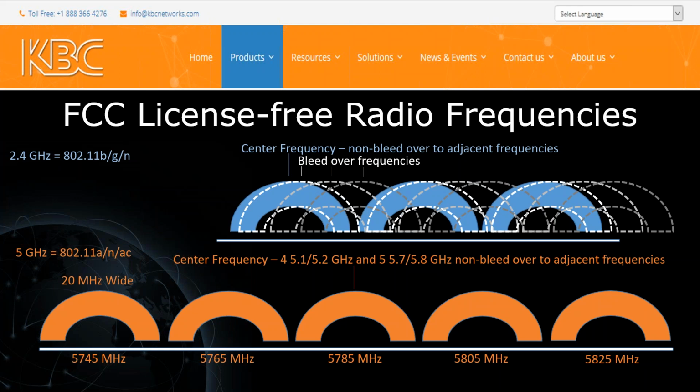Those represent the different frequencies that will not overlap with each other. So you could use 3 different systems, and you can set them on 3 different channels, and you wouldn't interfere with yourself. But there are a whole bunch of other channels that are available that all overlap. So that's one reason, as also a lot of interference and some other reasons, that we do not use 2.4 in our systems. It's just crowded and a lot of different bleed over, not very many frequencies. And also, kind of the last slide, you can do more with 5 gigahertz. You just need to have more line of sight.